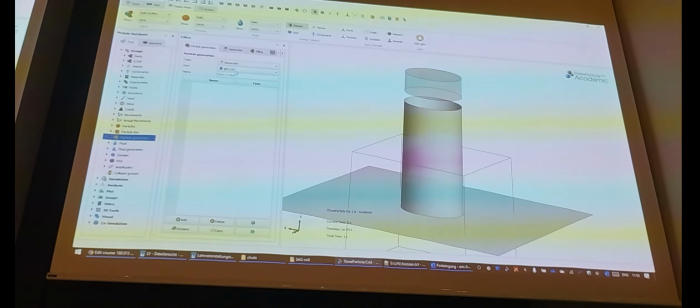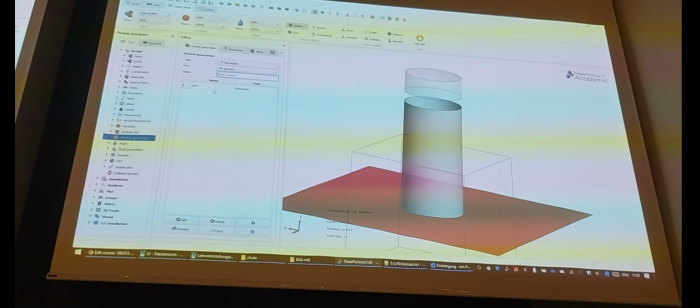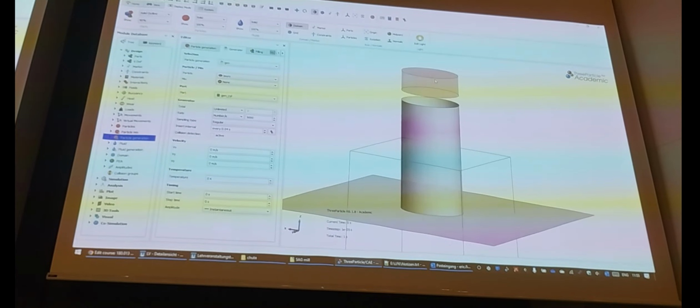Now let's start with the generator and say I want to make a generation from, and that's important, from the generator plane above or the generator cylinder above. If I double click it, I see it again. Now that should be red. The thing above your cylinder should be red. You so far with me? Either your plane or my cylinder should be red. Yeah, torus should be coming out there. Wasn't so bad before. Let's start with velocity. 2 meters is okay. Downwards. Start time and stop time, very important. Most of the people forget that. And that should be it.